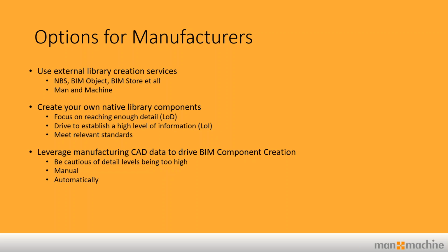The reason being is IFC is not designed to hold a family component. IFC is designed to hold an entire building, an entire structure of a building, an entire MEP design of a building. Revit won't let you place one component as an IFC. It will only let you link an entire design as an IFC. So you should not be using IFC as a building object. So we can actually leverage data from the likes of Inventor. And again, I'm going to show this live shortly.